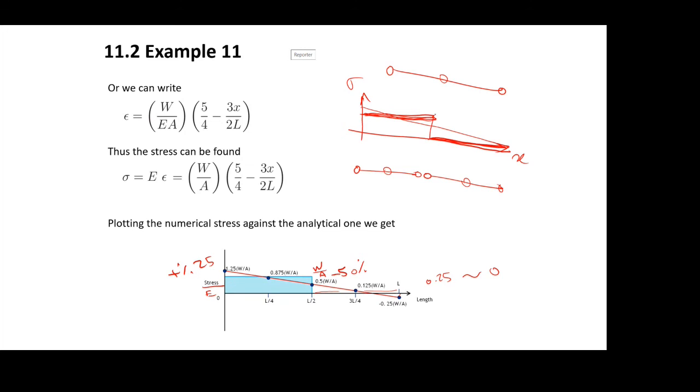And then on the interface, you have this discontinuity in the stress. The discontinuity in the stress is the nature of the finite element method you are using. This is called the Galerkin finite element method, and it is a basic feature of the Galerkin finite element method that you have discontinuity in the stress in between the elements. So the discontinuity is the nature of it, and then the line is going to fit the constant quite well, and the other line will fit the constant quite well.